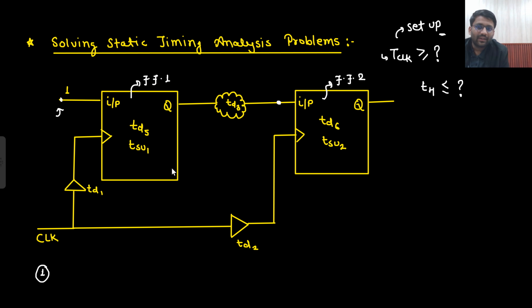Since this input is stable, I don't care about the setup time of this guy, neither do I care about the hold time of this guy. Is that understandable to you? So first we need to see whether the input is stable or not. Input is stable here. Job gone. Input is not stable here. Now this is my matter of concern.